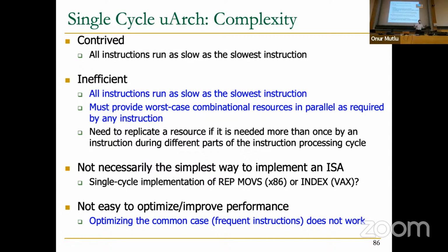You may say, okay, add is the most common instruction that I see, but it's not the longest instruction. So now you're dictated by the longest instruction to determine the clock cycle time, which is load word in this particular earlier case, right? So you cannot say, I'm going to optimize my clock cycle for the add, because it's single cycle. So it violates this common case design principle, and it doesn't work, essentially.